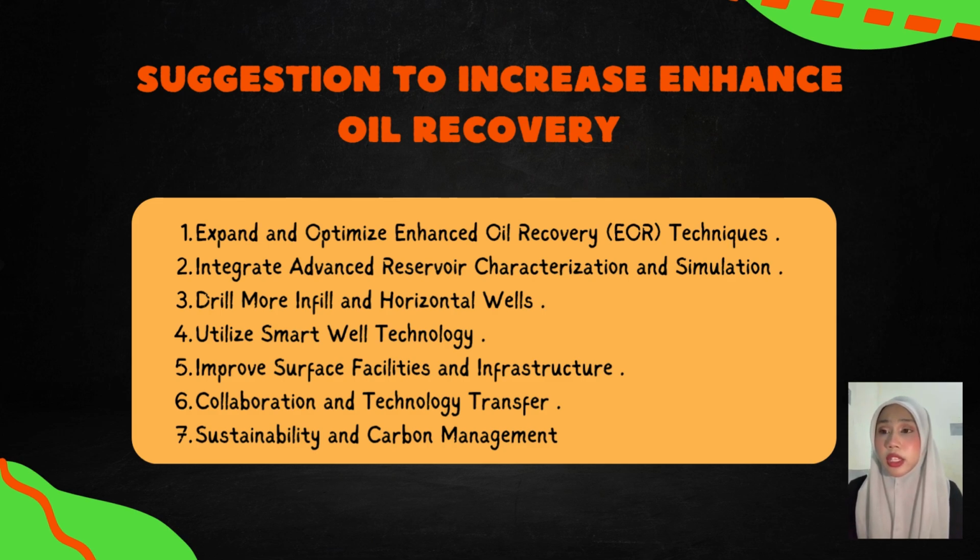The third one is drill more infill and horizontal wells. Increase drilling of horizontal and multilateral wells to improve reservoir contact and access bypassed oil zones. And perform infill drilling in areas where pressure and recovery are low to maximize reservoir drainage.